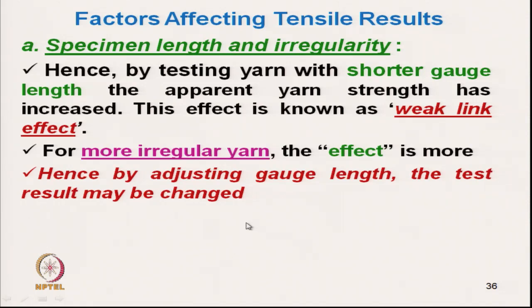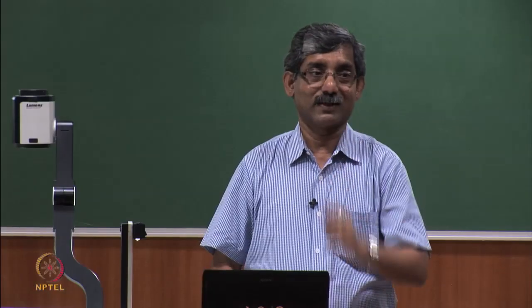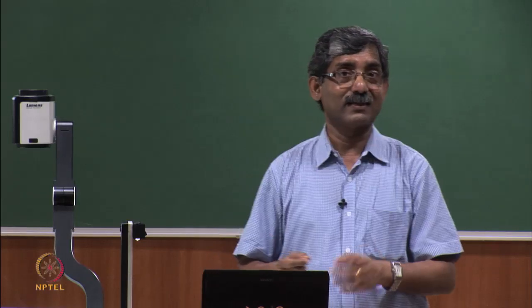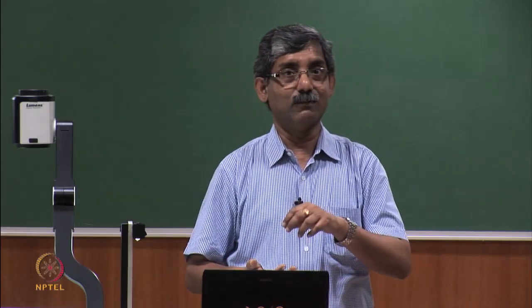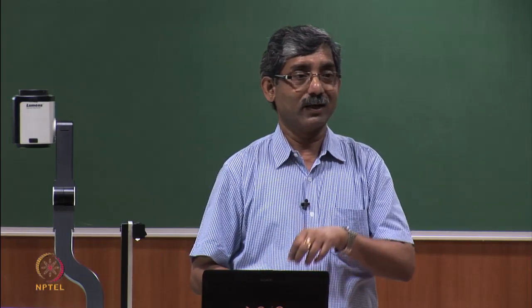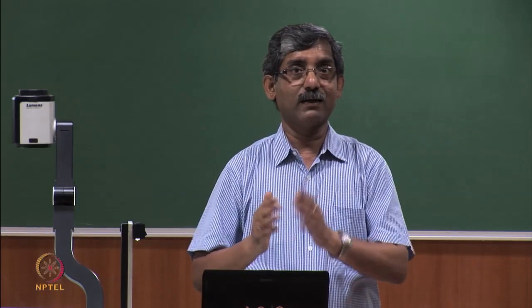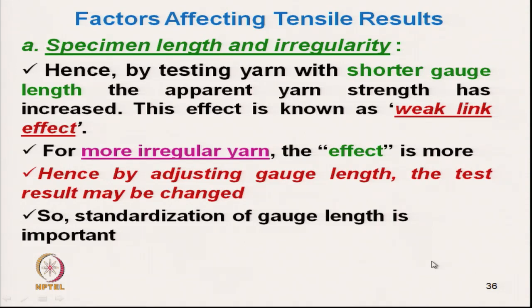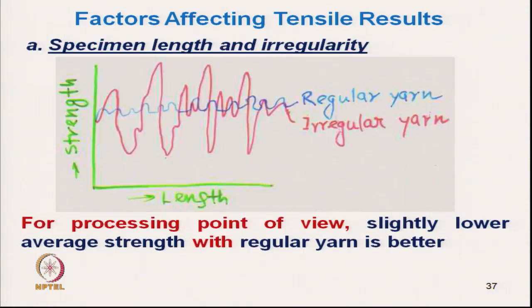That is why for any standard test, that gauge length has been fixed. In any testing, any tensile testing, gauge length is very important. It has got direct impact on the test result. So, standardization of gauge length is important. Now, you can see specimen length and irregularity.